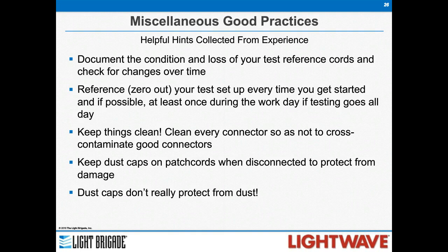They're starting to get worn. Connectors only have so many matings in them, so at some point, you're going to get worse results in your testing because your test cords are going to get old or damaged. So it's a good practice to record that off and on, keep a little log in your tool bag, and make sure that they're not drifting out of control. During the workday, if you're doing a lot of testing, re-referencing your loss test set will help keep you on track as well. And again, keeping everything clean, keeping your work area clean as well will help protect everything. That's just a great practice to get into.